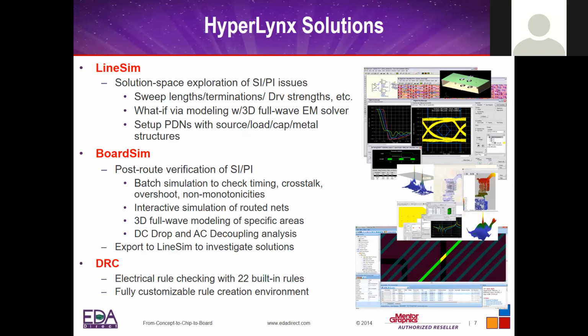And once your board is laid out, and before you fabricate the board, this is the last chance to run the analysis again. This is when everything is known. The trace lengths are known, the number of vias are known, the chip vendor has been selected, the connector has been selected, and all of these things. You should run it again. Make sure that your clocks are clean, your resets are clean, and check for EMI issues that you may have. Those are done on the post-layout side.